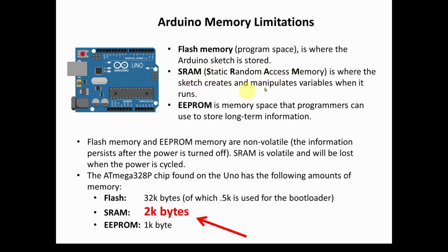We're going to have to take a look at that, because if we don't have enough memory and we try and store a bunch of samples and we run out of RAM, we're going to get crashes and all kinds of problems. So that's why it's really important, as I've said before, not to just start writing code. Plan it out and see what you're going to need to make sure that you've got enough space and enough speed to make sure this is going to work. So SRAM is going to be a big factor.